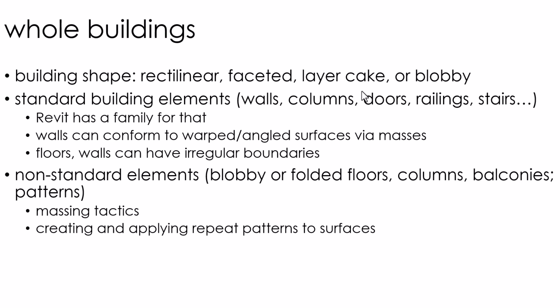And Revit, of course, is loaded with families that can create these standard elements very easily. And you can even customize them to a certain extent. You can make windows with rounded tops or doors that are octagons instead of rectangles. And they will still cut openings in walls. They still behave like good old Revit objects.